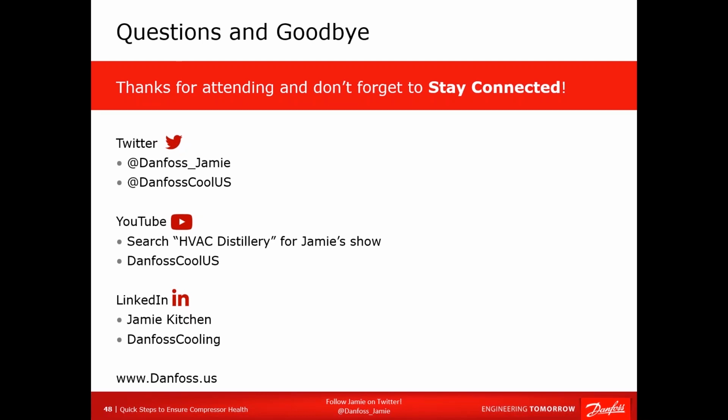Some people prefer to use the evaporator superheat, but again, the manufacturer will specify where to measure it when you're dealing with charts. If I don't see where to take that measurement, I default to the compressor. Some people may use the evaporator. Either way, if you can ascertain that you have a correct range of superheat, you're good to go. I just like doing it at the compressor because that's what I've always done, and it's pretty easy to get to most of the time.